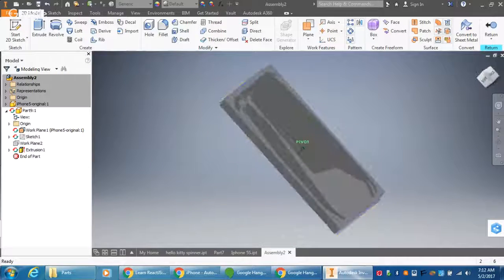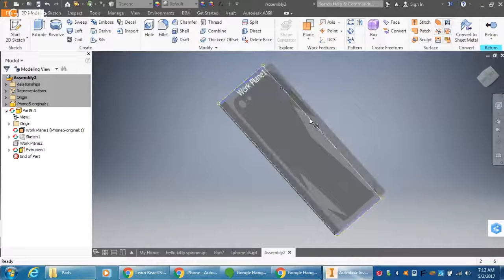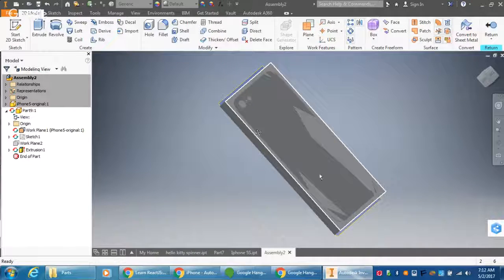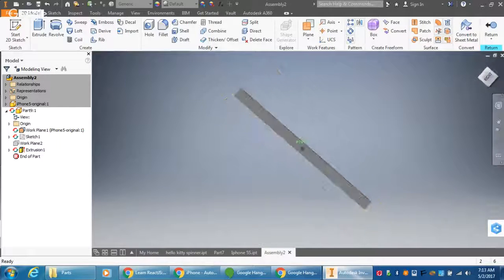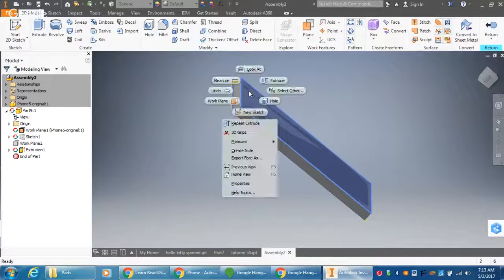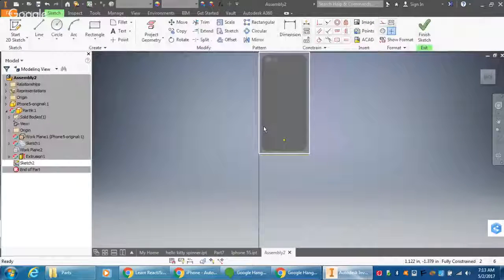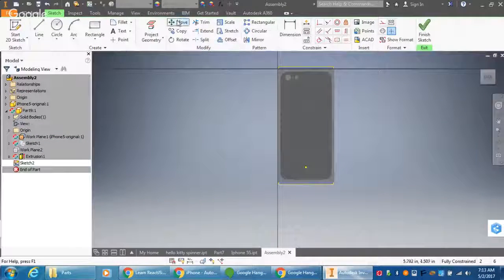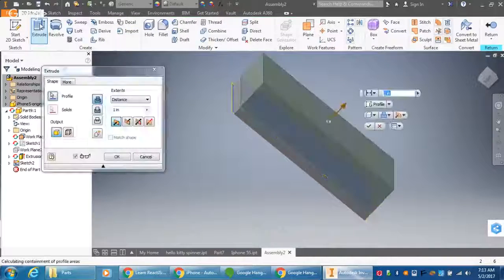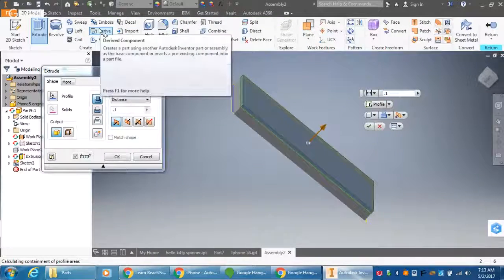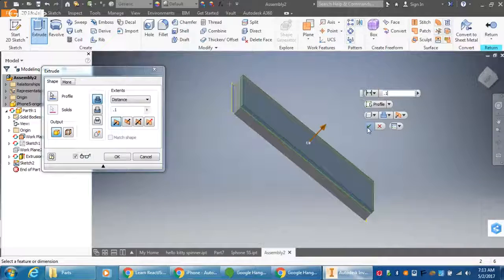Now, for what I'm going to do, in my case, I'm going to build off of this. I really don't want to have anything in the center over here because I'm going to make a different style this time around. However, if you want this back here to be a little bit thicker, you could always place a new sketch here. So I'll show you this. Let's place a new sketch here. And I might as well do this. I'm going to go ahead and project geometry, finish that sketch, and I'll extrude this 100 thousandths again. All right, just to kind of make this consistent.